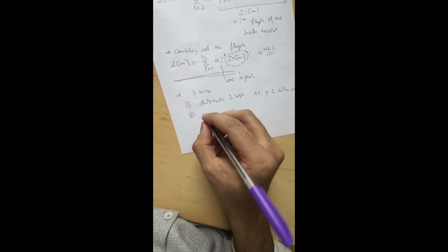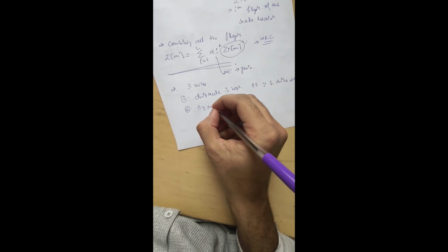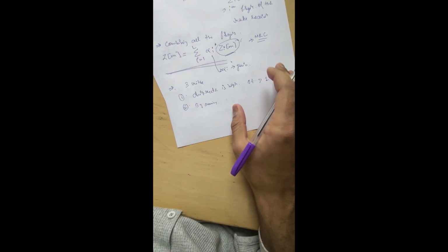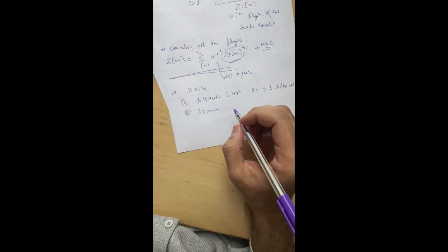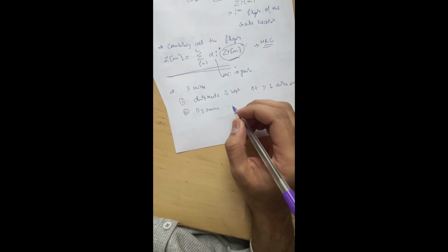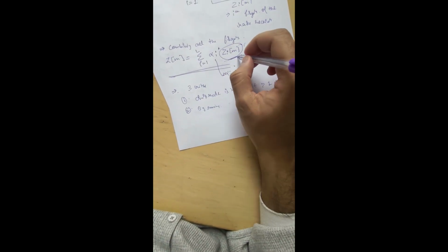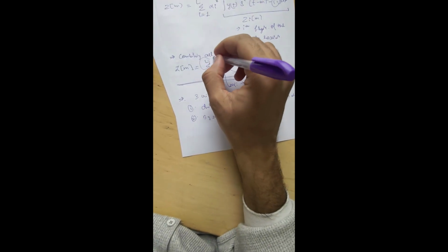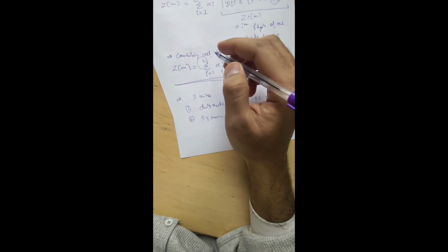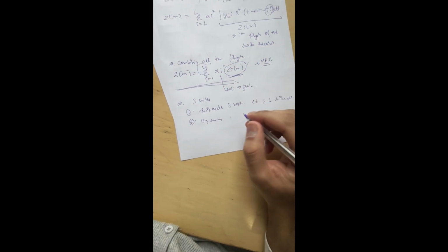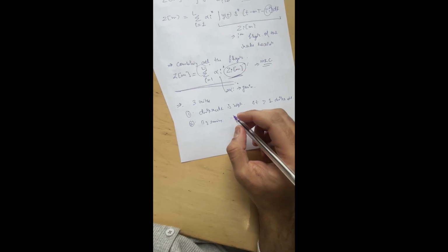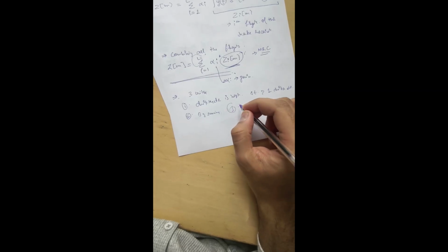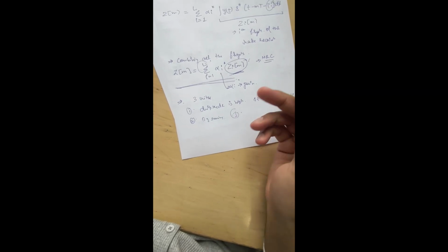The second point is that by summing these paths, we aren't just getting more power, we are also protecting ourselves against fading. When we sum all the independent paths, it is highly unlikely that all the L paths are in a deep fade at the same time. There would be at least one path, by probability, that won't be in a deep fade, and that path would give us the required SNR and the required channel information.